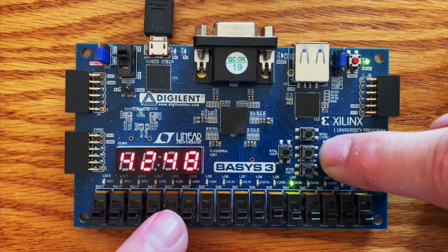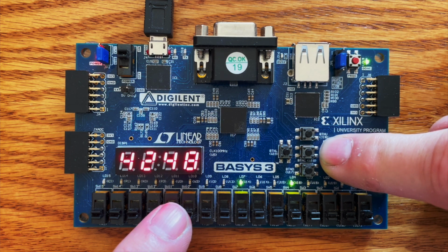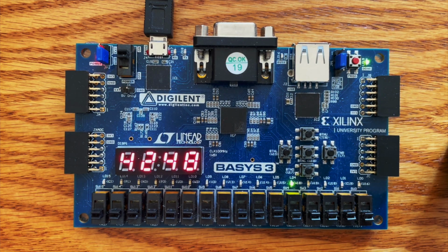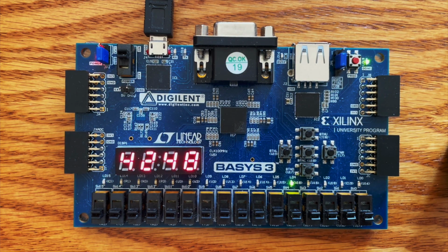While looking at LED 11, release and re-push the right push button. You should be able to see LED 11 quickly flash on and then off. It happens really fast, so you may miss it. This is the signal which clocks the value set on the switches into the divisor register. We're now ready to run the division state machine again.